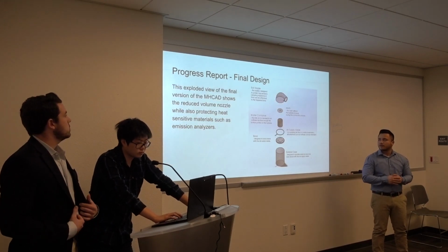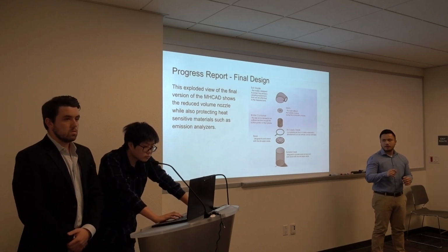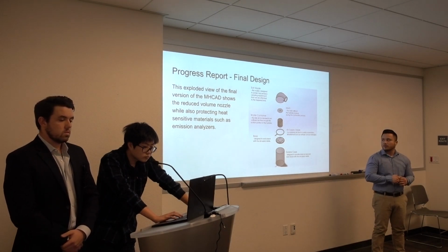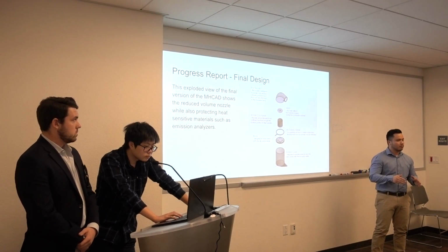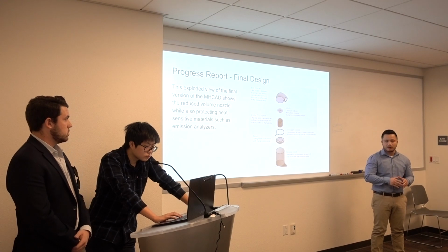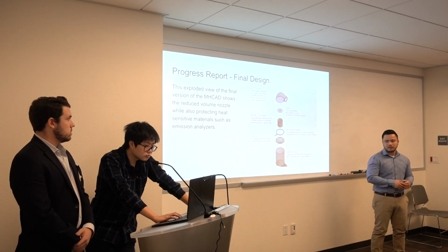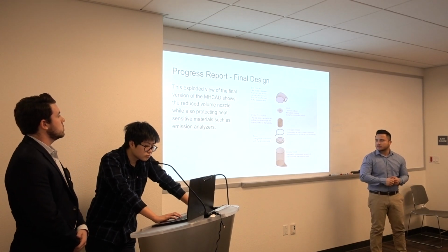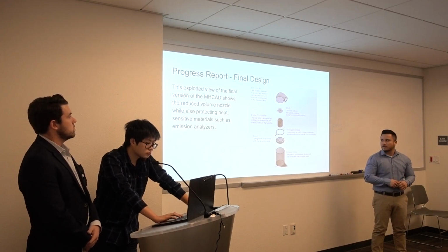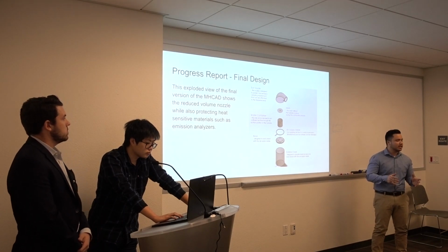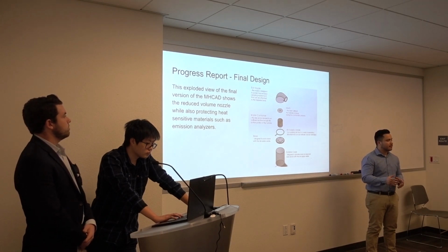We came up with our final design, and it is essentially a cylindrical chamber with a tapered 90-degree elbow nozzle. We came up with this design specifically because within the cylindrical chamber you have the possibility of laminar flow if you have the appropriate air supply tool. For that, we chose a cylindrical tube that will deliver the air through small holes around the diameter of the ring. With that, we'll achieve zero pressure disturbance within the combustion of the methane hydrate itself.